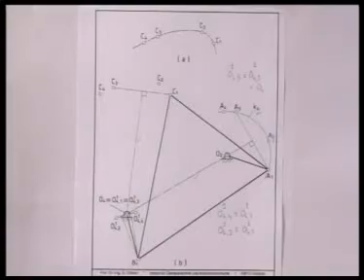Let me now summarize what we have learned today. Initially, we used the 3 position synthesis technique in multiple stages to achieve the design of a 6-link mechanism. Then we discussed how to do 4 position synthesis for both function generation and path generation problem with respect to a 4R link.